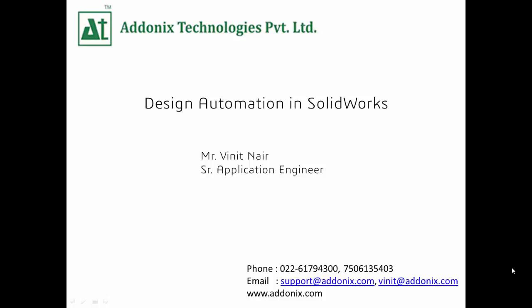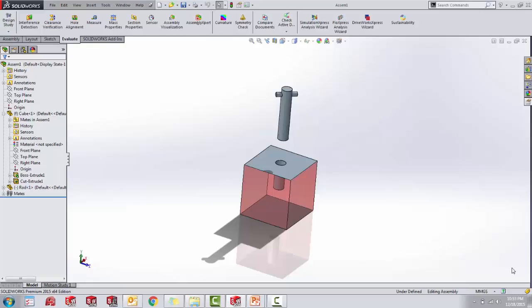In SolidWorks, as far as I know, there are three ways of automation possible. First, using design table. Second, using macros. Third, using DriveWorks Express. DriveWorks is an add-in available in every seat of SolidWorks, even in SolidWorks standard.